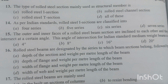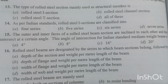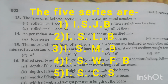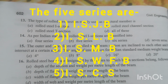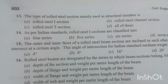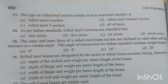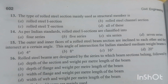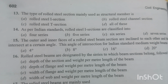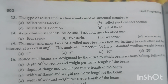Question number 14. As per Indian Standard, rolled steel I sections are classified into 5 series. Option B is the right answer. And the 5 series are ISJB, Indian Standard Junior Beam, ISLB, Indian Standard Light Beam, ISMB, Indian Standard Medium Weight Beam, ISWB, Indian Standard Wide Flange Beam, and ISCS, Indian Standard Column Section.